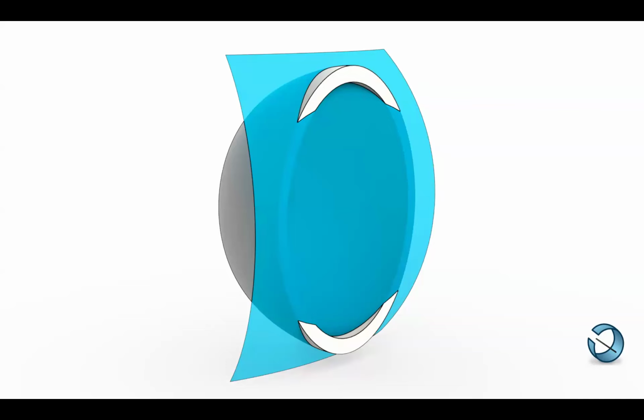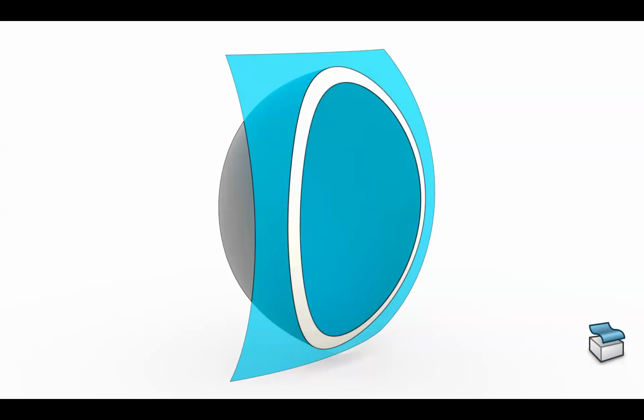Right? This is not just cutting with the surface, but when you replace the face, there's a specific replace face tool. That's what you end up with. Right? It just takes the existing flat face and just replaces the definition with whatever that face is. And it can be a multiple surface, multiple face surface. It can be complicated if you need it to be. It can be a really handy way to take a simple shape and make it much more contoured with a replace face.